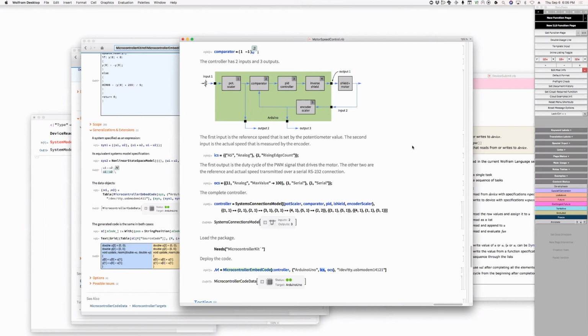So you connect the thing to your computer, it pushes the code into flash memory, then you disconnect it, and as soon as you put it on a battery, it will start running its program. Is that correct? Yes. And if you want to monitor it, that's for debugging purposes. That's when the device framework comes in, so we can read stuff. I understand. So that's the way that we can peek and poke at this microcontroller. Yes.